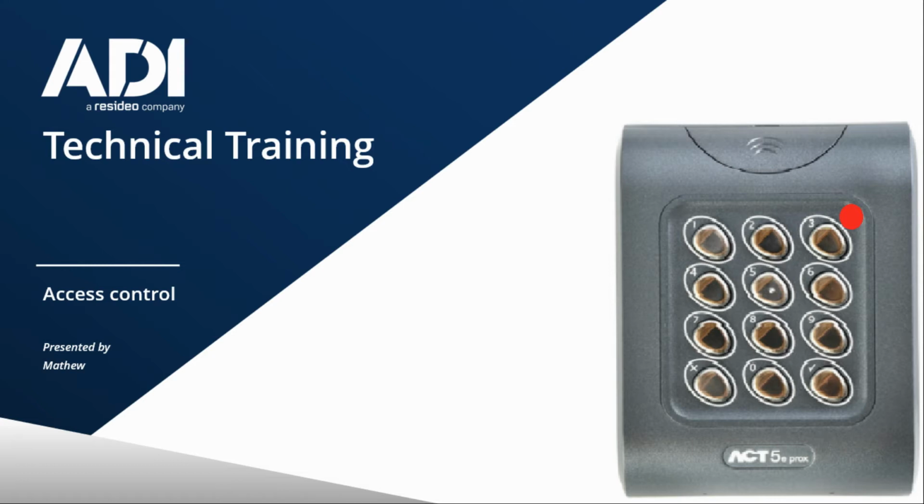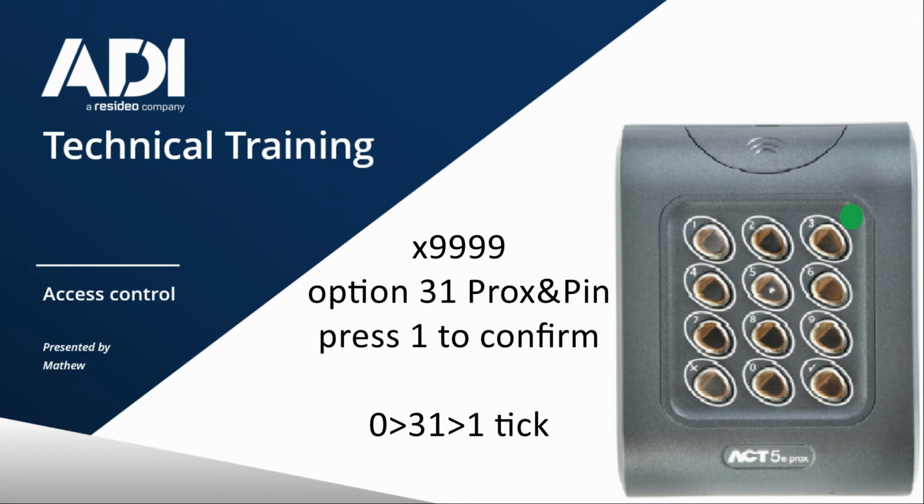Now, if you want a bit of a high security application, where someone has to present the token, then type in the PIN code, we need to enable pin and card function. I'm just going to check I picked up the right token. It is here. Right, so we need to get back into the engineers mode, and this time we need to go into option 31, and that option 31 is card and pin.